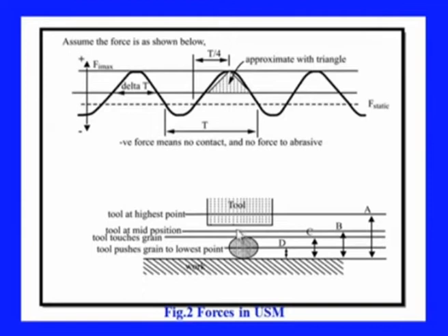Then again it will start decelerating, and when it reaches here, this is the minimum position it comes to, and then it starts pushing the abrasive material against the workpiece surface, and the abrasive will move through or penetrate this work material hereafter.